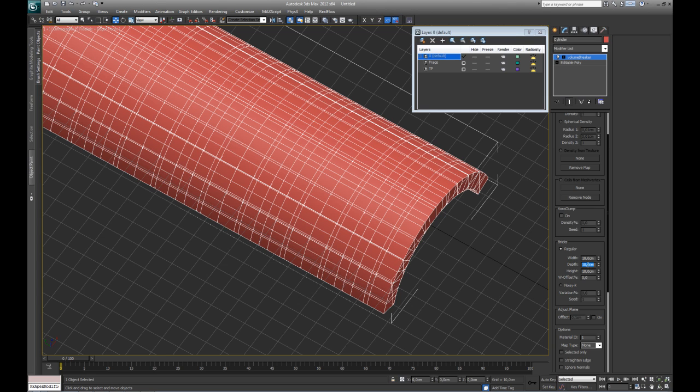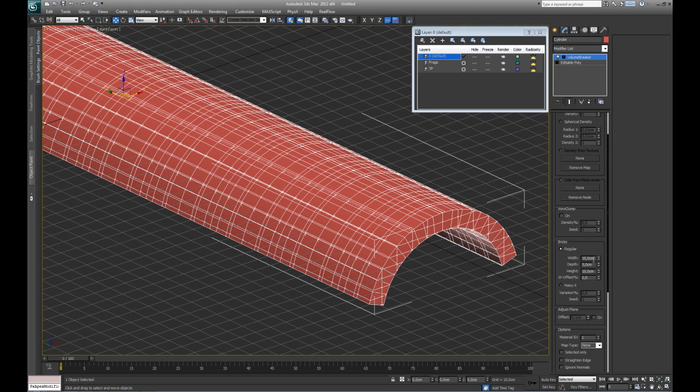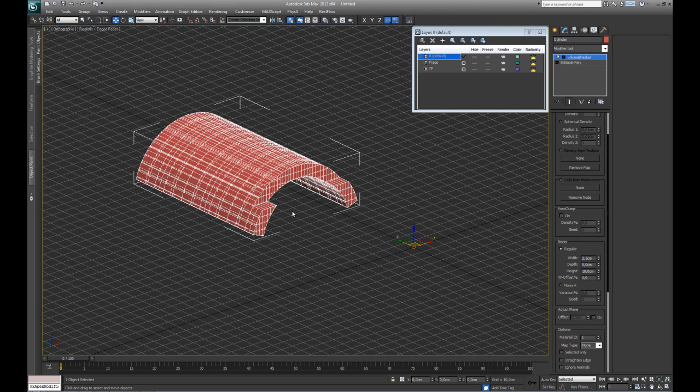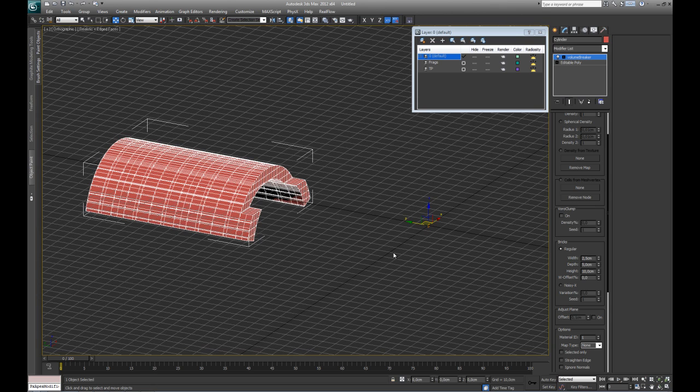And I'm gonna put in some settings. One thing that you have to take care of when you're using this is that if you go too low with your values, you will see that it will start cutting wrongly because it can't really figure out how to cut the rest. I'm not sure if it's a bug, however it's just how it works. So sometimes you will have to do this in multiple passes, where you first do big bricks and then take the big bricks and individually use the Volumebreaker on them afterwards.